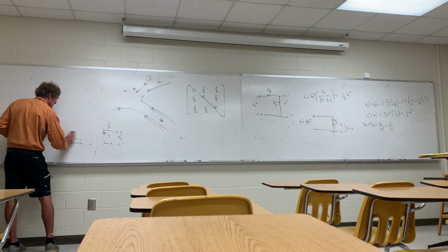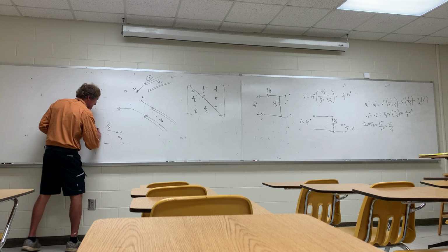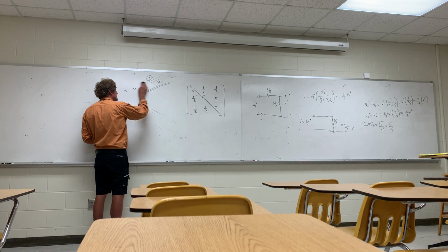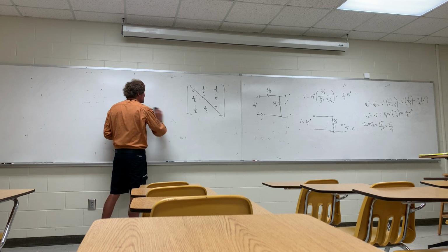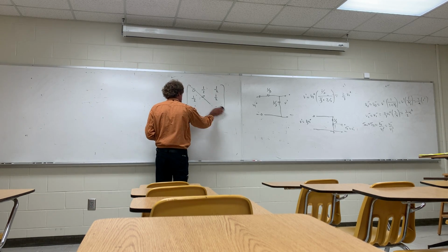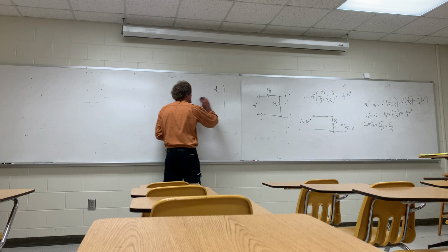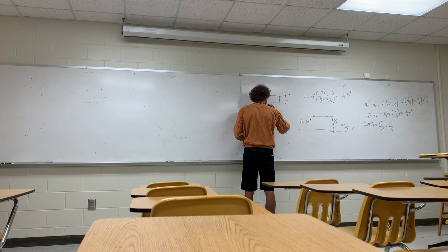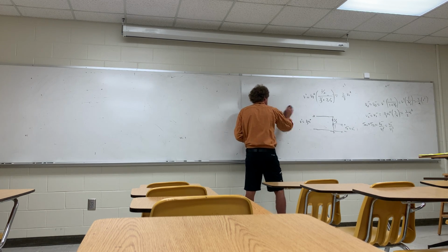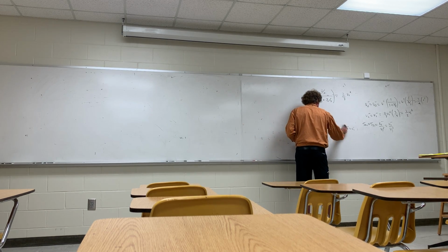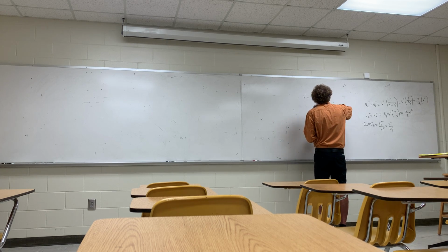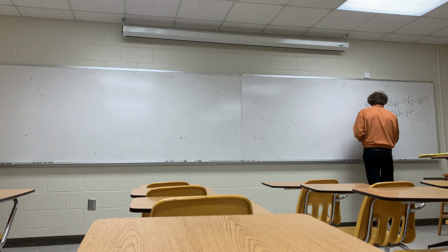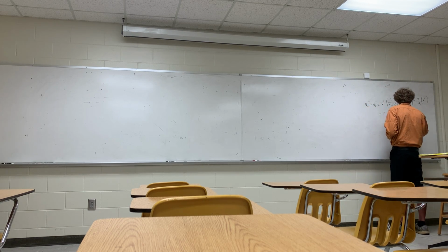They are used when they fabricate circuitry. Wilkinson dividers are used. The bad part about a Wilkinson divider is it only works for a small band of frequencies. It's designed to work at a certain frequency, ideally, but it'll have a band of frequencies, so you can get some deviations where it doesn't work efficiently. Now, that resistive network doesn't care about the frequency. You can have it work on any frequency you want.